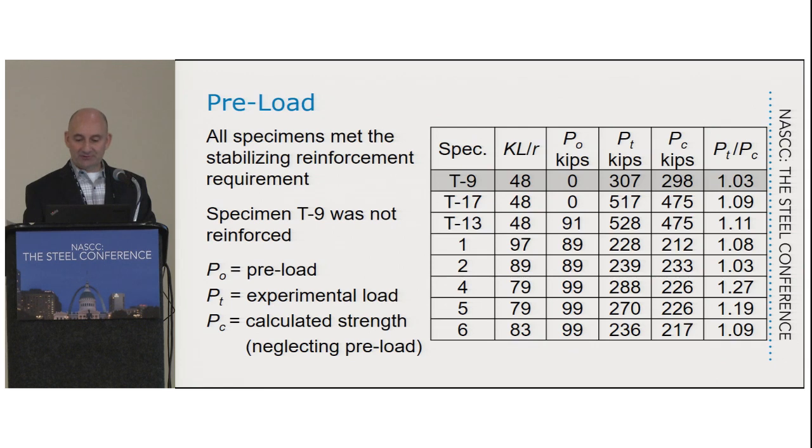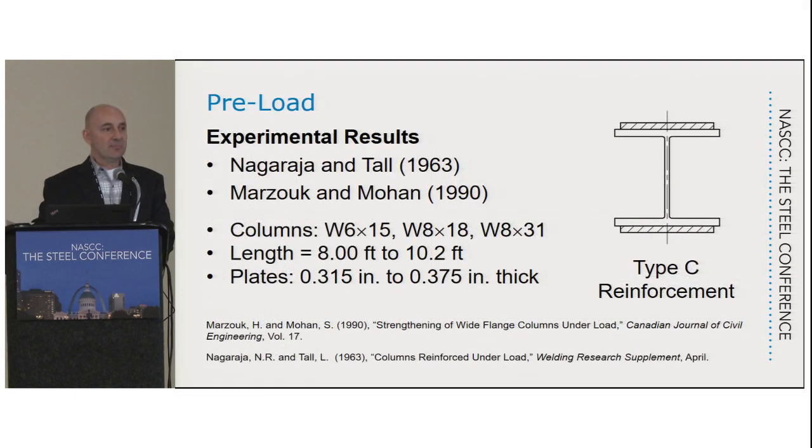And the reason for that, at least theoretically, like I said, there are other things that can explain the differences, but theoretically, what happens is if you have a wide flange shape, you're going to have compression residual stresses at the flange tips. And compression at the flange tips, remember the flange tip is the area that we're most interested in to contribute to the efficiency of this column to prevent it from buckling, to provide resistance to buckling. So the flange tips are farthest in both the weak axis and the strong axis from the neutral axis. Okay, so we want those to be elastic as long as we can, but a compression residual stress plus a compression applied load is going to cause it to yield earlier than if you had no residual stresses. All right, so that's your normal condition, and that's the AISC column curve.